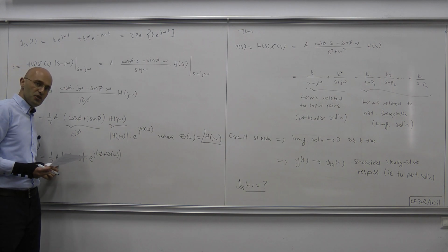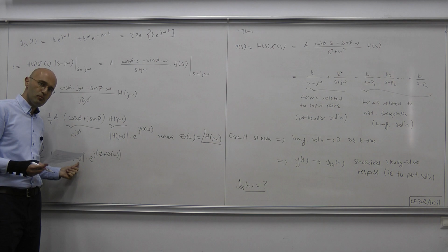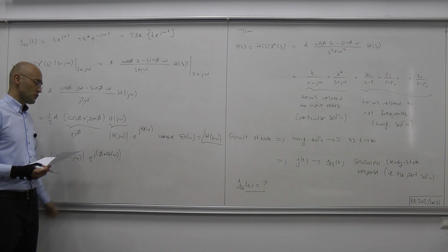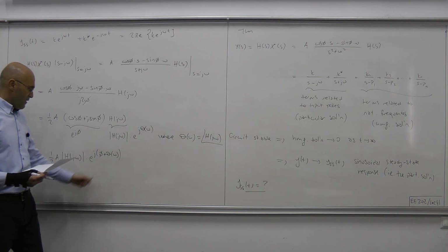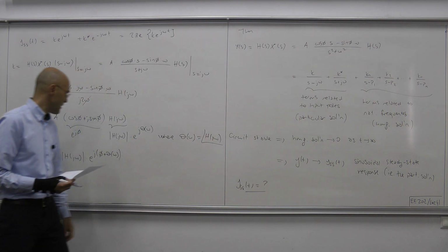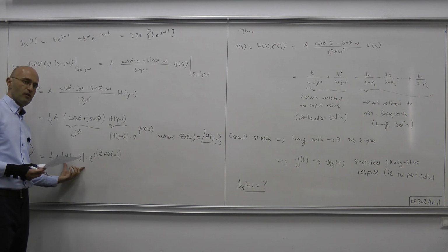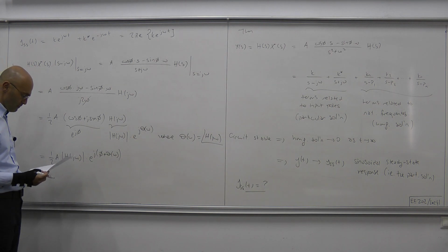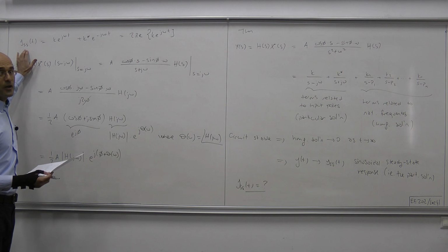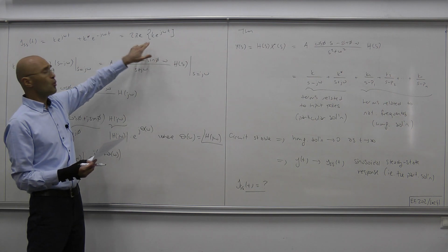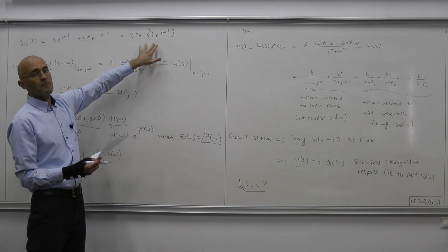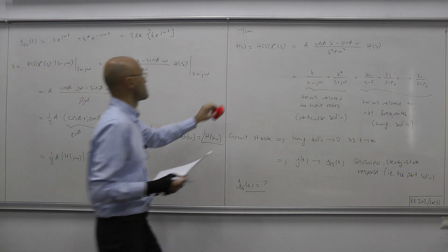A is coming from the input, it's the amplitude of oscillations. And omega is coming from the input, it's the frequency of oscillations. Okay, and then theta is the phase of the transfer function evaluated at s equals j omega, and this is the magnitude of our transfer function evaluated at s equals j omega. Okay, now having figured out K, we can now try to write or compute YSST, the steady state output, the steady state solution, using this expression here.